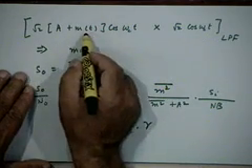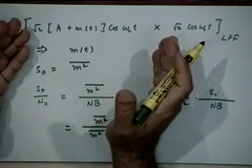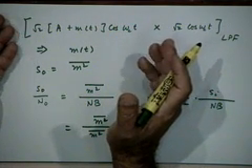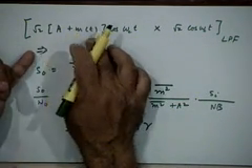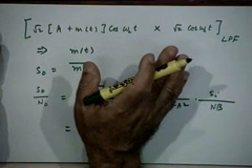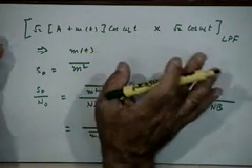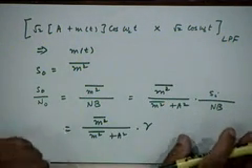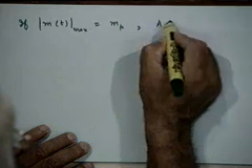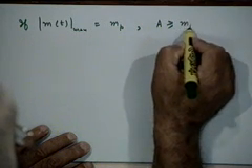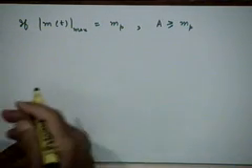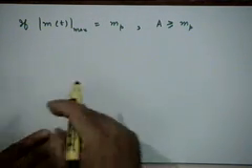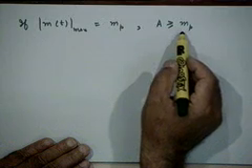Because if you remember, your A plus m(t), for synchronous demodulation that is not very important, but typically you would keep your A plus m(t) to be positive, right? Although for synchronous demodulation that is not a requirement, that is the usual condition. Basically, what does it mean? That A will then be greater than or equal to m sub p, because if you have a negative peak, for example, A plus m(t) should still be positive. So the value of A should be greater than or equal to m sub p.